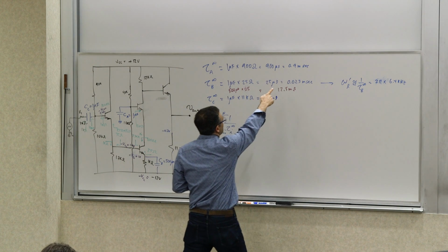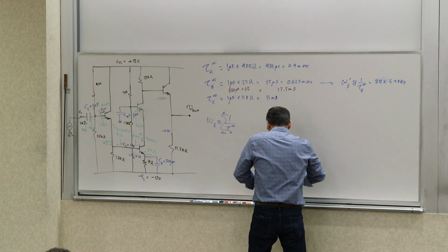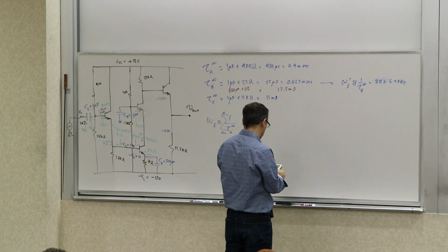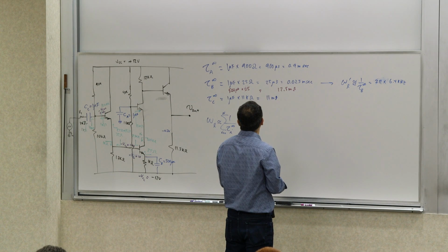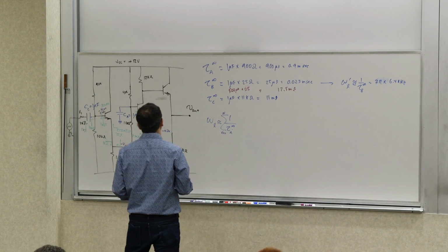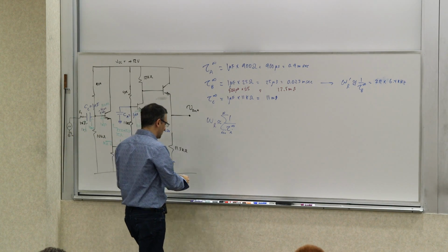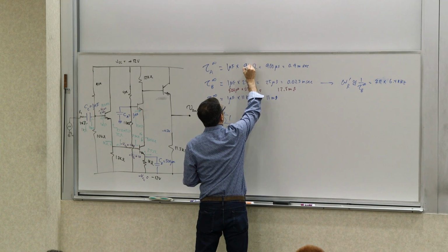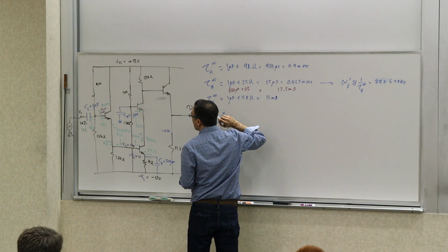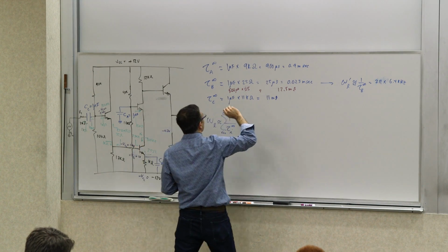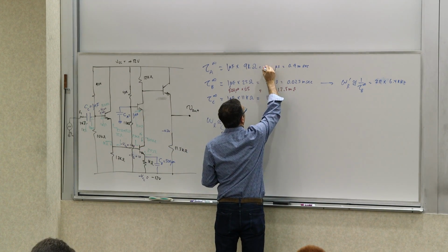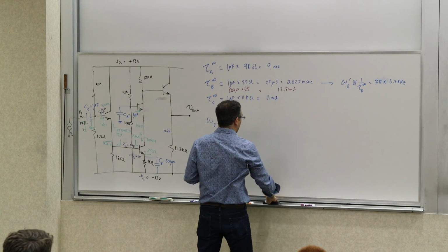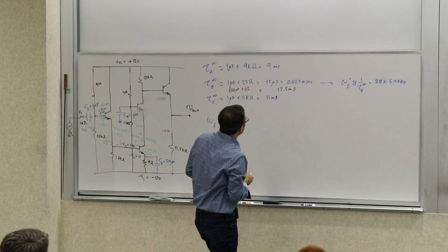So I can calculate what the reciprocal of that is. Should that have been 900 ohms or 9 kiloohms? Sorry, which one? I thought it was a 10K parallel to a 9. Yeah, it should be 9. Yeah, you're right, actually. This is 9 kiloohms. This should have been 9 kiloohms. Oh, no, yes, it should have been 9 kiloohms, sorry, yes. So this becomes 9 milliseconds. Let's make that correction. So now they're on the same order, so you can actually approximate it.